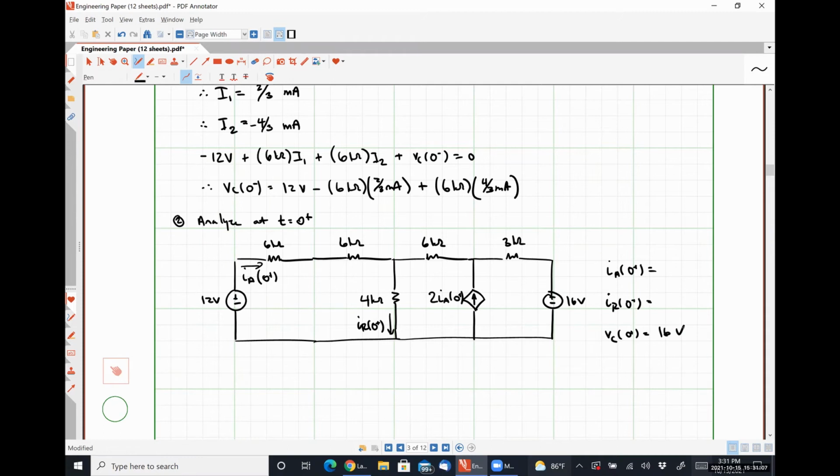All right, those are the two. How could I go about solving this circuit for these two currents of interest, Alexis? I would combine the two resistors in series and then do the nodal. Okay, so for this one, nodal and mesh are probably about the same, although actually now that I think about it, nodal will be a little bit easier because you only have two unknown quantities.